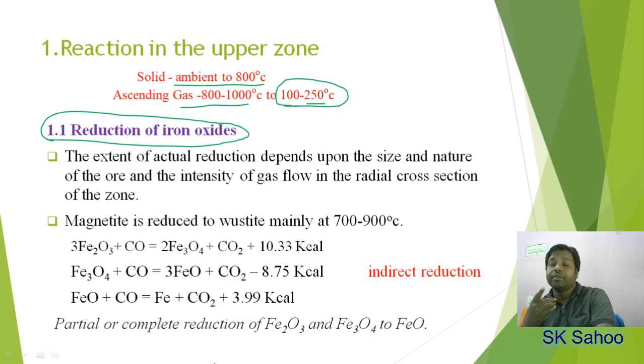When we talk about the Ellingham diagram with respect to partial pressure of oxygen, Fe2O3 is at the top of the plot, showing that it has high oxidation potential and is highly unstable. So a little amount of carbon monoxide can reduce it to its lower oxide, Fe3O4, the magnetite. So this reaction is instantaneous and completed within this region.